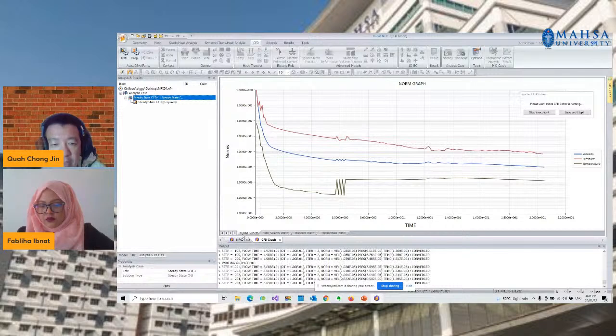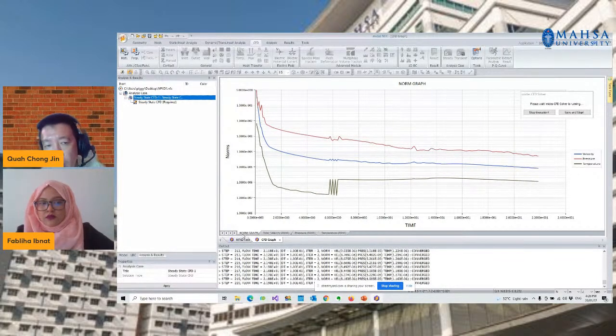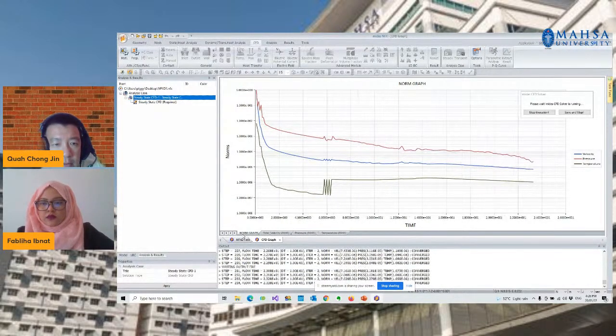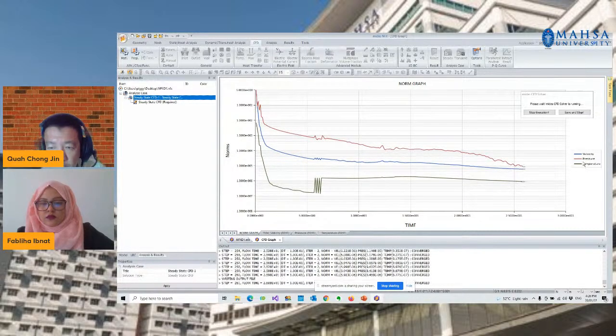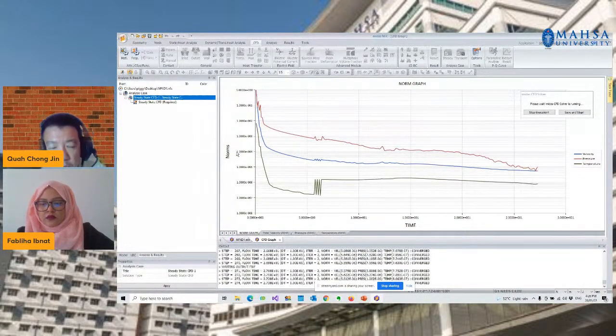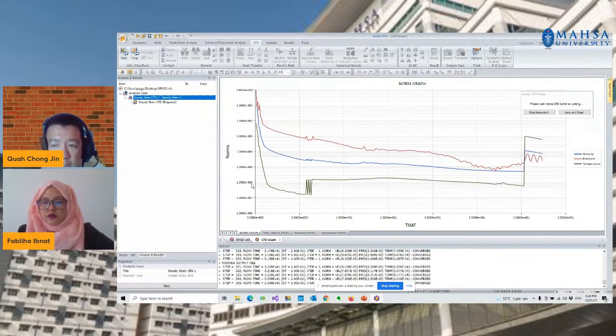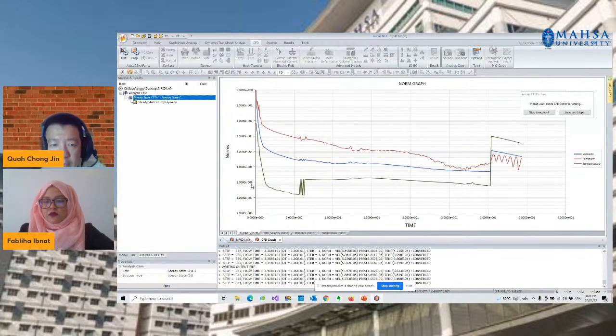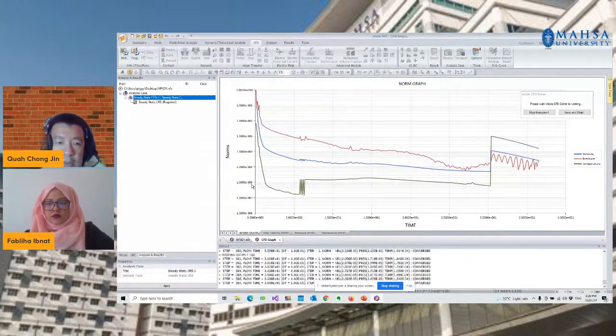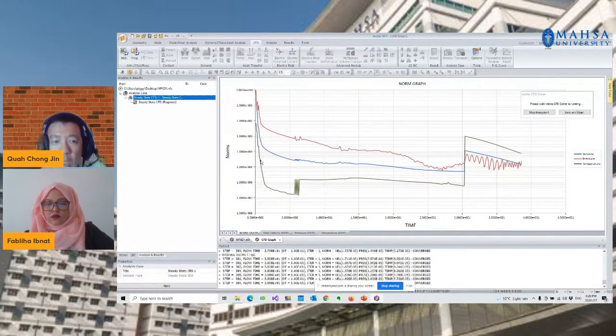So the error should be 0.1 or 0.01 or 0.001. In this case, we have an error for pressure which dropped to 0.0001, which is to the power of -4, to the power of -5, and so on. So this is the first thing you have to ensure. Make sure that all the residues or the norms fall below 0.